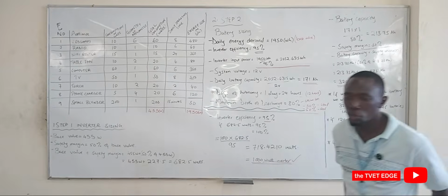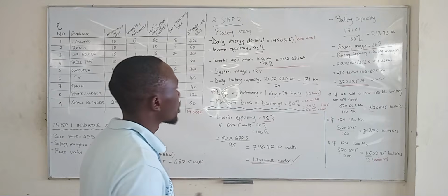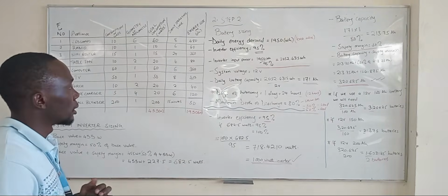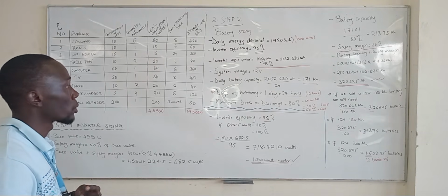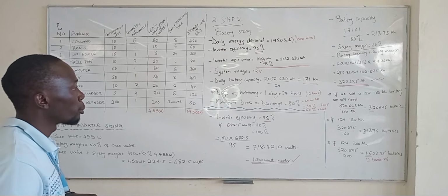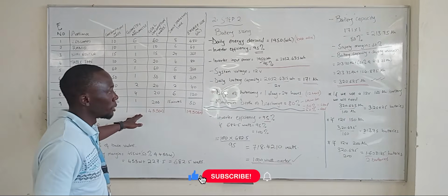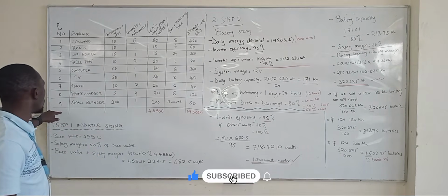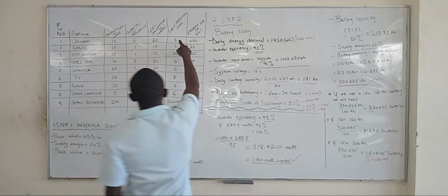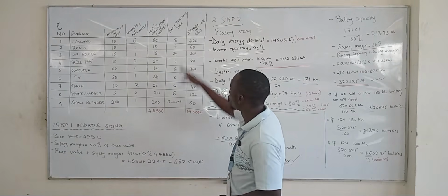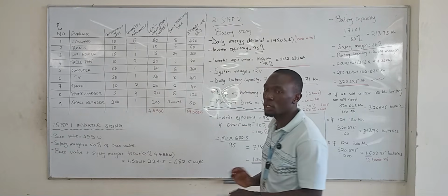Now, this was just a basic revision, but I intend to use these same values to develop our charge controller, to determine the capacity of our charge controller and the solar panels. So you could pause at this point and do some basic exercises up to this stage. Introduce probably 2-3 other loads or appliances. You could change the daily operating time, because the minute you change some of these values, they could either add or reduce the daily energy demand. So just do a few exercises.